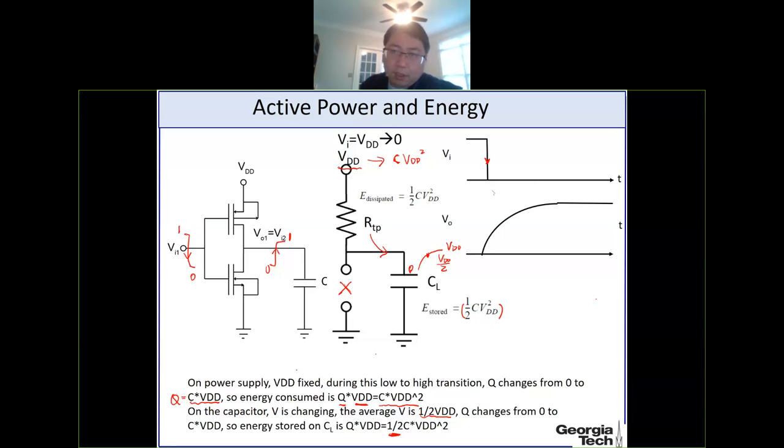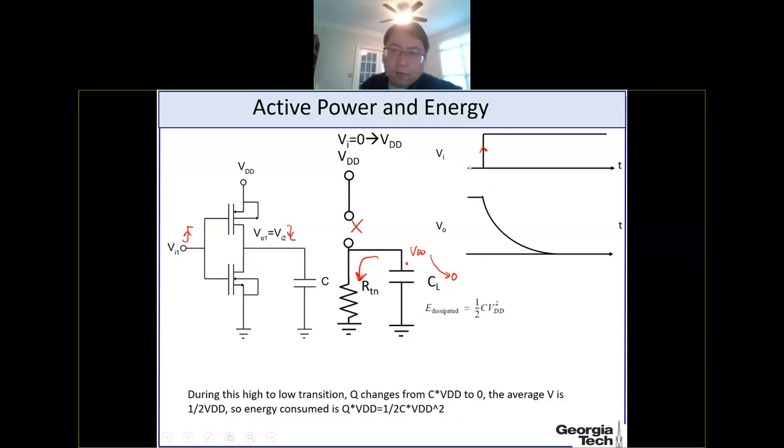And then the next half cycle, where the input is switching from 0 to 1 and the output needs to discharge from VDD to ground. This is pull down, and we discussed before that for pull down the NMOS is working, so the PMOS here is off. So the NMOS is working, and the charges here will be discharged through the NMOS to the ground.